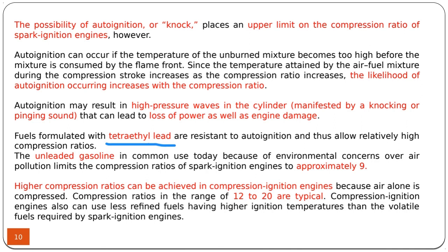So typically, gasoline engines can have compression ratios between 12 to 20, depending on the engine design. But normally, without any fuel additive, it's limited to 9 because of the material and knock conditions. Of course, this cannot be exceeded because of especially the material conditions.